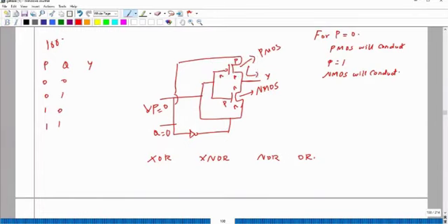So what is F? F is in terms of sum of products. Here they have given A is your MSB and C is your LSB. Okay. So it is given, it is a sum of products, and you have 3 variables. So you have to draw the 3 variable table. So with 3 variables totally you have 8 cells, right? A is the MSB and C is your LSB.